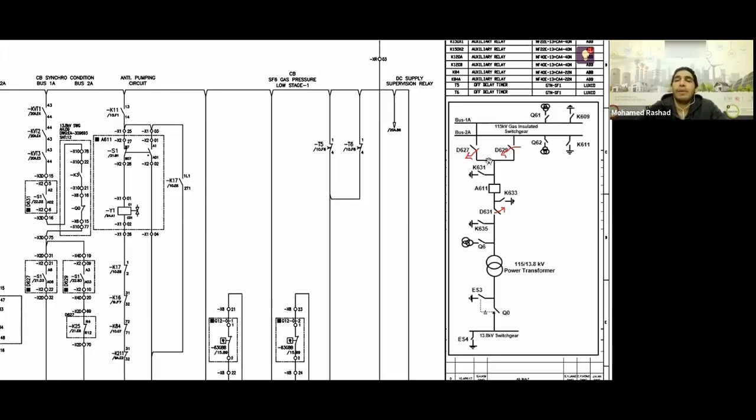Someone might say to me, but you explained to us and told us that even if it's open, I might get from the upper and lower bus bars, those that are before, to the part that comes after this one. Or you might also get something called induced voltage from the line. You told me at that time that in order to discharge the static charge, or this induced voltage, to bring it down to 0, what do I do? I must have a ground before and a ground after the breaker so that I can reach the 0 voltage point. And as a person dealing with the breaker, I am then in a safe position. This is done by grounding, guys.